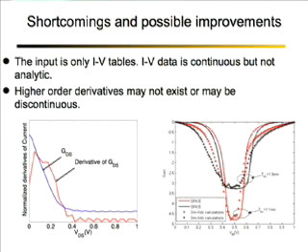What we see is that although the results seem to match pretty well with the SPICE generated results, the SPICE results are shown in the solid line, and the dotted line shows the results generated by PETE, we see that there is a good amount of numerical noise wherever there are sharp discontinuities and at the max gain point. This is due to the fact that gain, which is essentially GM divided by GDS, has discontinuities, and this comes up in the plot of gain versus V in.